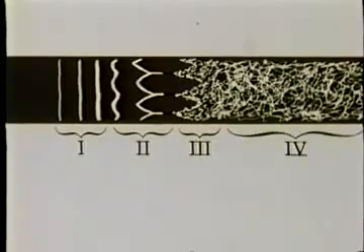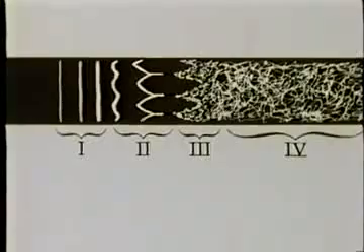Here, the exact position where growth of two-dimensional disturbances begins depends on random small-scale fluctuations in the flow, and therefore varies with time in a random way. This boundary layer around a channel bend is made turbulent by placing an obstruction in the layer upstream. The obstruction stimulates the naturally occurring processes and hastens the onset of transition.